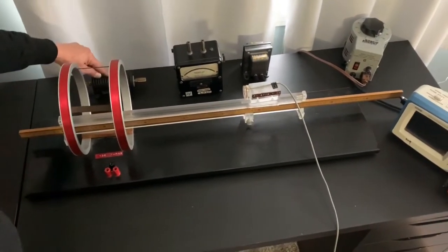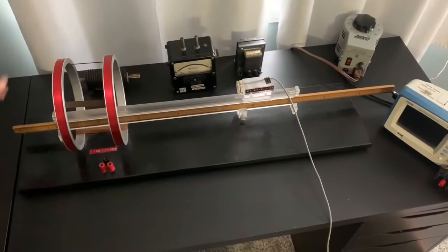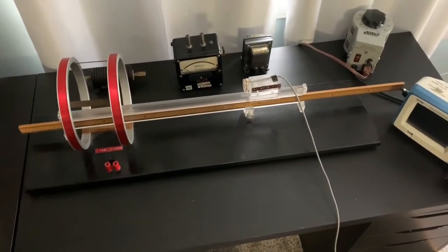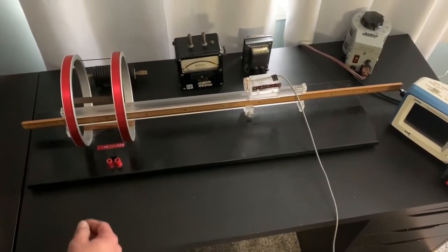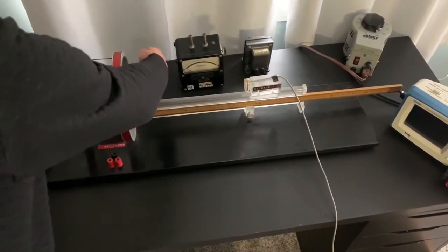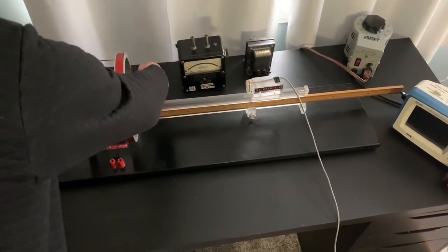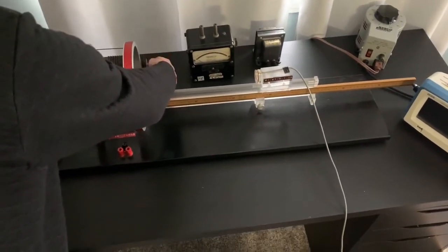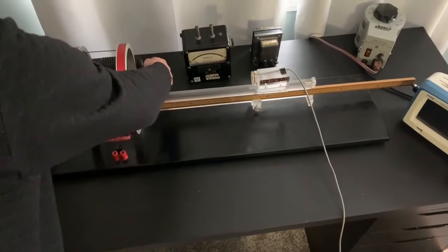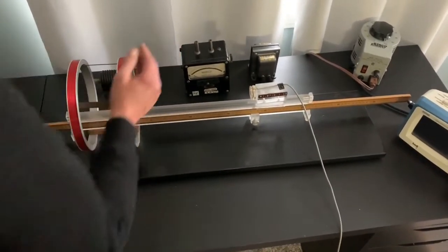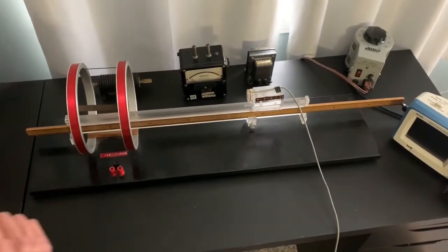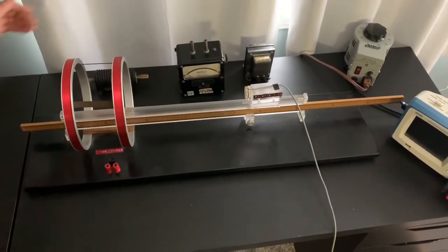We'll also have this resistor hooked up in series so that we can monitor how much current is actually going through our circuit. We do that by hooking up in parallel the oscilloscope, so that at any given instant in time, I know what the voltage across this 1 ohm resistor is, and in effect, I could calculate the current through my circuit at any time.